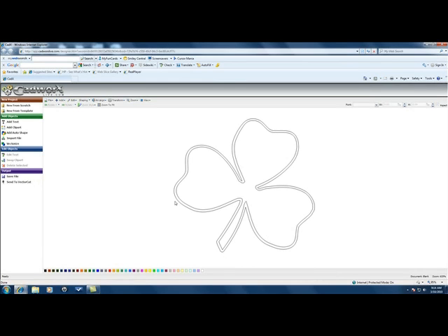I'm going to add a line to the outside. If I select my graphic, and this is important to know on all your different graphics, to go from layer to layer, just use your tab key. You can see right now I'm on the outside layer, and I'll select it again. I'm back on the inside layer. If you have a graphic that has a lot of detail, the tab key is real easy to go from layer to layer. So I'm on the outside line here.